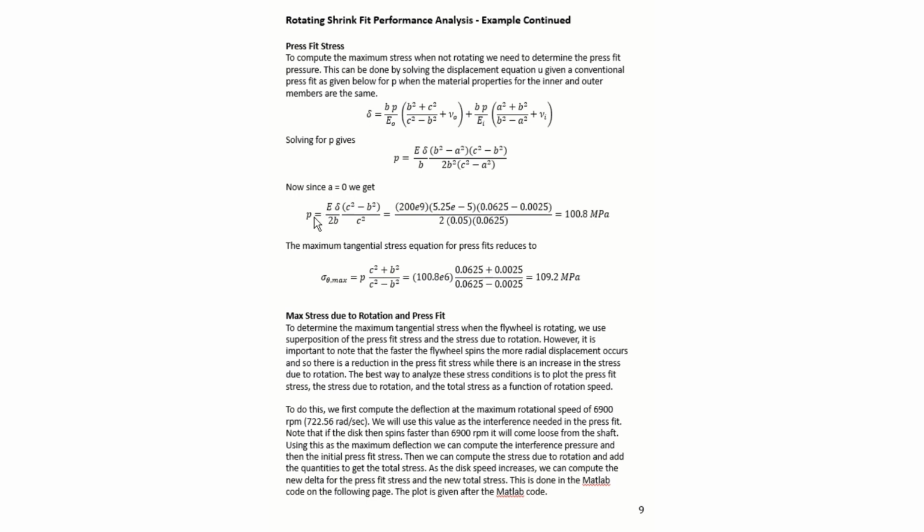So based on this pressure, the maximum tangential stress can be determined, and it is computed to be 109.2 megapascals. So the sigma theta max is given at the inside radius of the disk, and it's computed to be 109.2 megapascals.